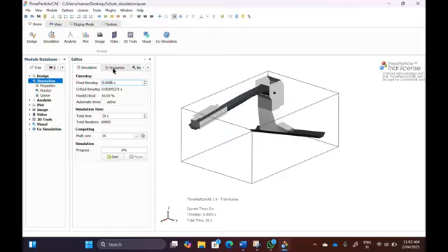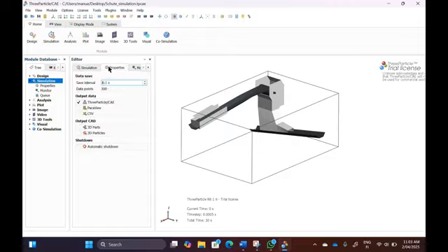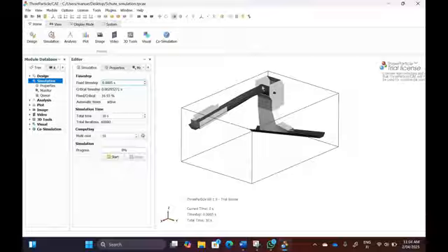That's really important. If I change the time step or something like that, for now, it's definitely not in the software. It's something in the system. Either it's the wrong path, so you have no writing access. Typically, it can be an error if there is too little space available on the place where it's simulating. The graphics card could be one error, but to be fair, not a very common one. The CPU is a common error. Some of them are not supported, especially the older ones. It shouldn't be the case.